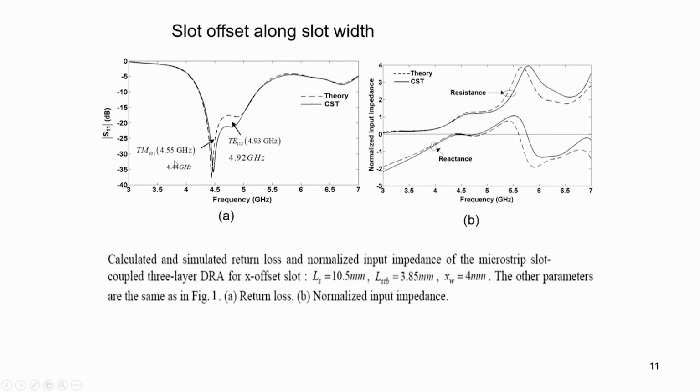there might be, and possibly would be, a change in radiation characteristics because of the change in the modal type on the left side, closer to the lower resonance, and the right side, which is closer to the higher resonant frequencies, because we have the end fire mode on one side, the monopole like mode on one side, and the broadside mode on the other side. Okay. So, for an X offset slot, if it is for indoor applications, we may not bother a lot, but in case we want stable radiation characteristics, then we need to be very cautious about the X offset.